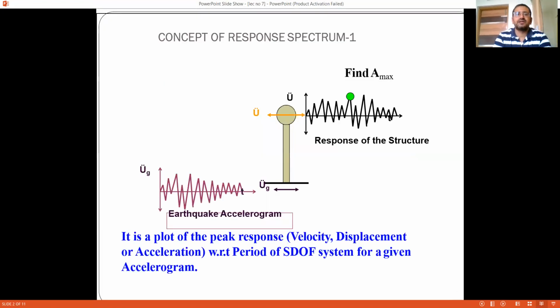Okay, so when you talk about the concept of the response spectrum method, the concept is such that whenever a horizontal acceleration is generated at the ground level, that is, ground shaking is initiated or the earthquake force is initiated at the ground level, these waves travel to the surface of the earth and come in contact with the ground surface or the structure residing on it. Once they come in contact with the ground surface, based on the soil profile, whether it is soft, medium, or hard type, these waves propagate and transfer the forces to the structures constructed above the ground.